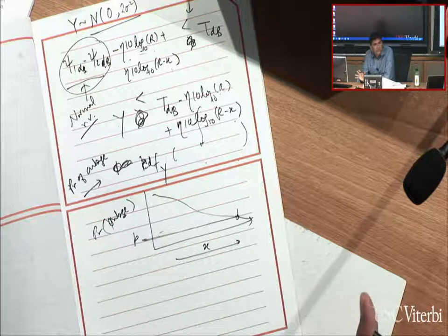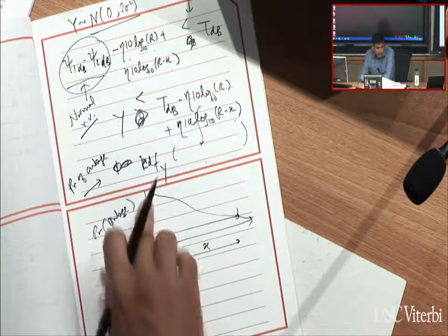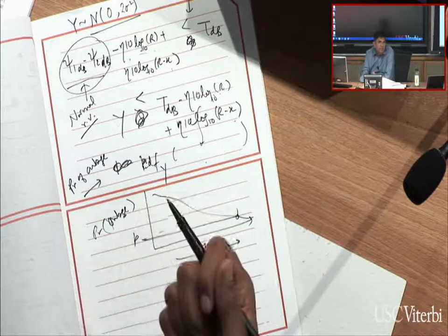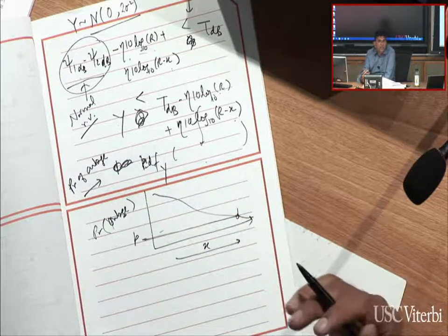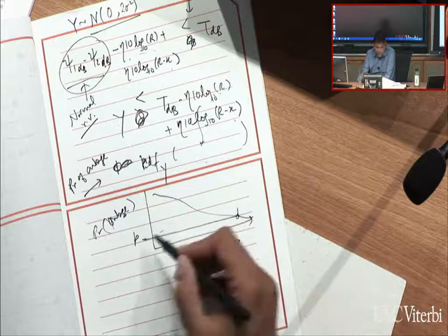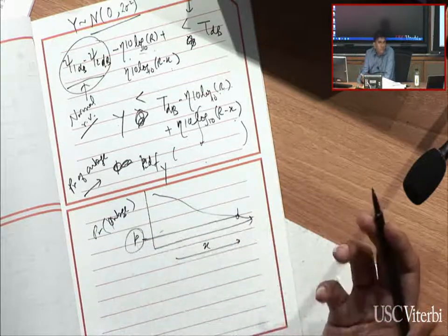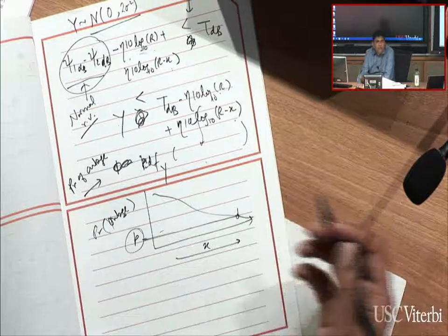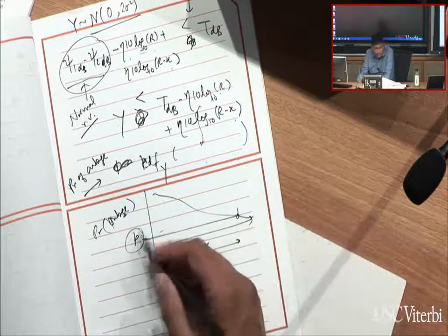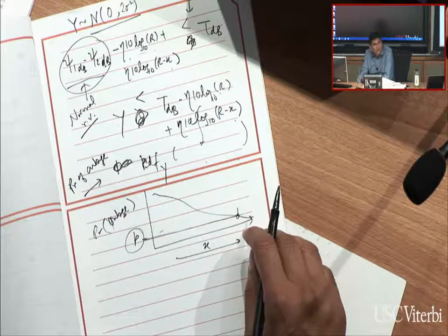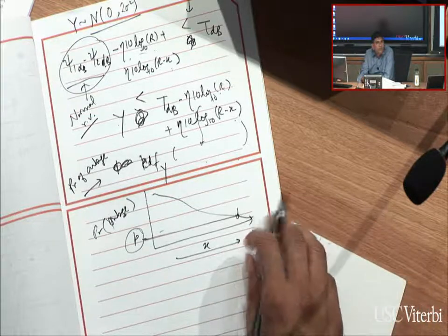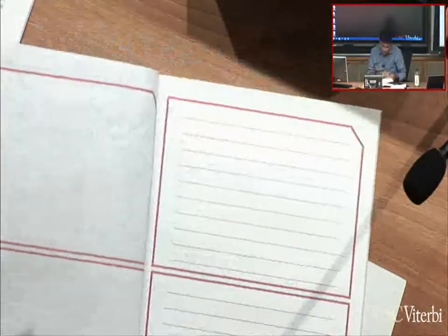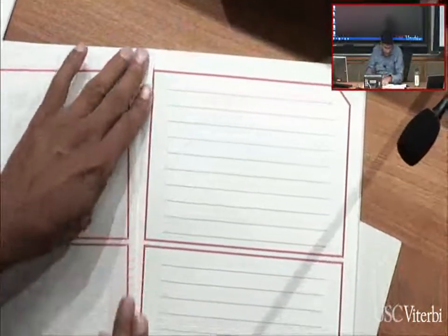So certainly if I chose a very small threshold, you would imagine that I would need a farther separation between the base stations. But if I chose a very high threshold, then I don't need them to be apart by much, because I'm okay to tolerate, let's say, a very high chance of outage. So it would actually depend on P. The answer to that question was sort of, it depends on P. But if you had the intuition that at high variances for small values of P, you're going to need a bigger distance, that's really what I was looking for anyway. So that was for the problem involving the base station location.